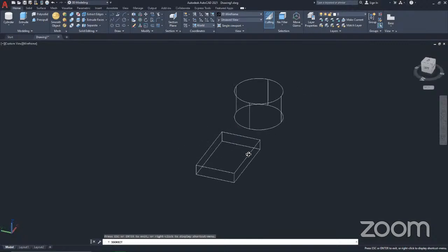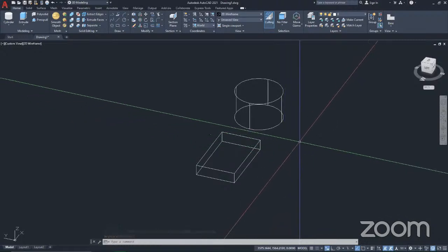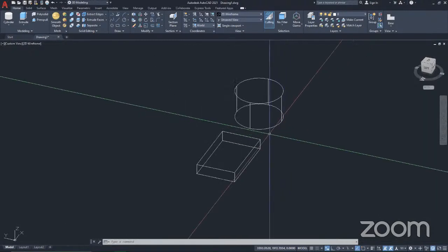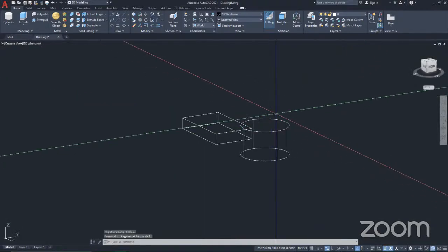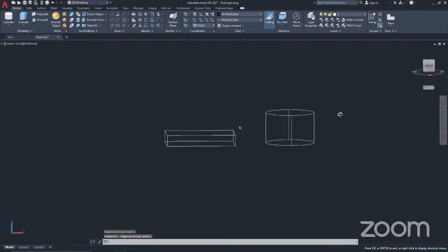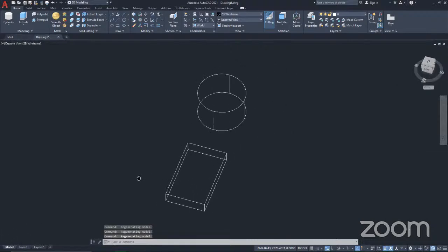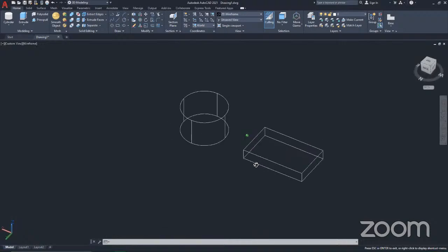So that is it, as you have seen. Alternatively, if you hold down your shift key and press down your center mouse wheel, the one you use in zooming in and out, you can actually orbit. That works perfectly. I use it all the time alongside panning. This is for panning, but if you hold down shift, panning becomes orbiting.